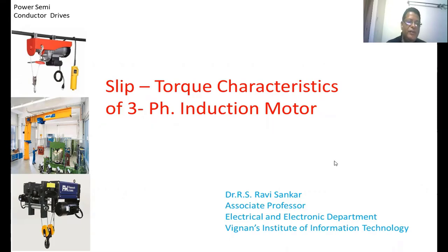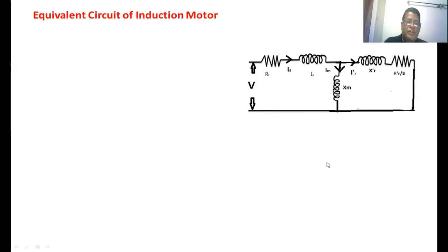In this lecture, we are going to discuss the slip-torque characteristics of a three-phase induction motor. So first, let's find the relation between the torque developed in an induction motor and the slip of the induction motor. To derive that expression, we start with the per-phase equivalent circuit of a three-phase induction motor.